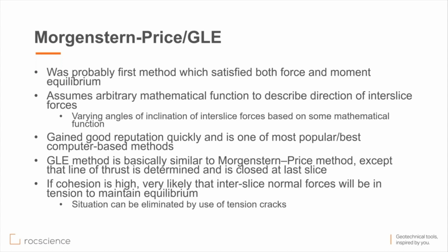When you have very high cohesion, what happens is that your interslice forces, when it tries to solve the equilibrium, can generate tension. And we'll see whether this is acceptable or not. But sometimes, to eliminate the tension, you will need to apply tension cracks in your model.